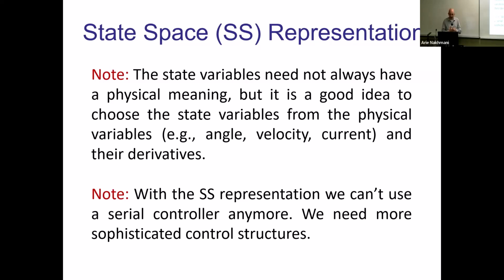Now, unfortunately, with state space systems, or maybe fortunately, I'm not sure, we cannot use serial controllers or feedback controllers as usual, like block diagrams where you see controller times your plant, and then you have a forward loop, and then you're closing that with a negative loop. We need different structures here. We need different types of connections for state variables and for state controllers. But they will be much, much, much easier to design because it will be like one line in MATLAB.